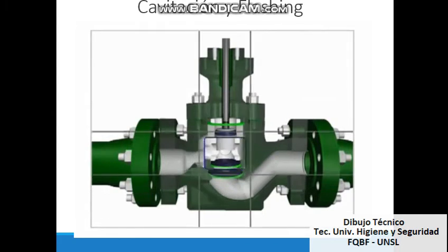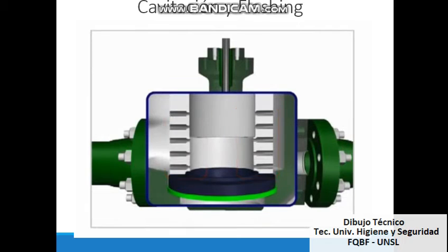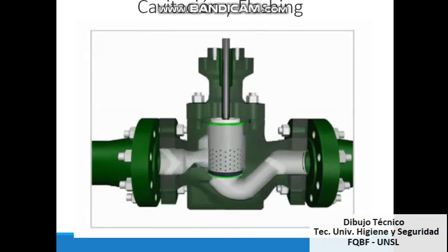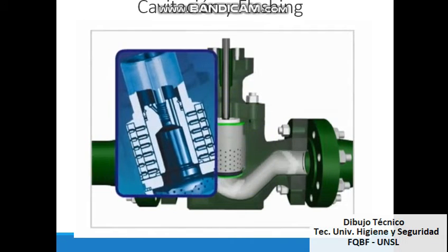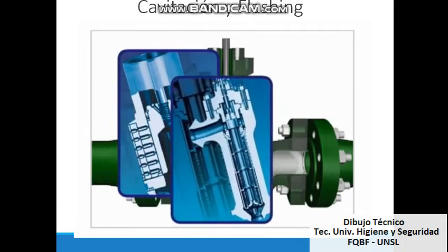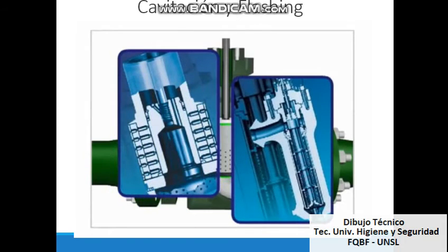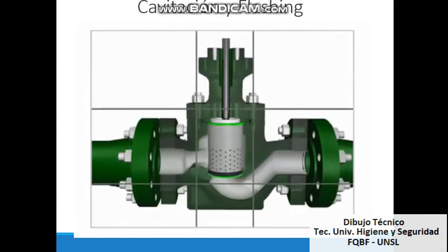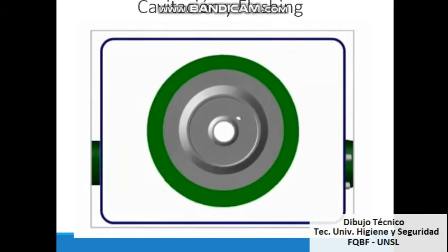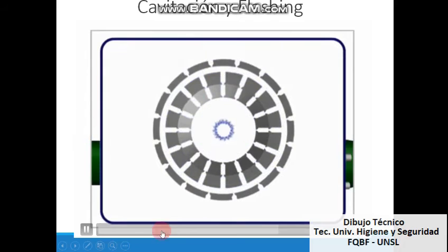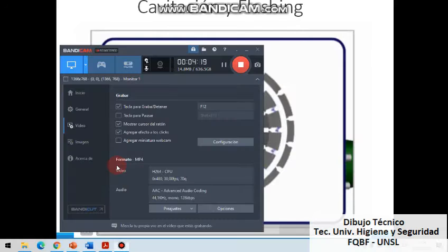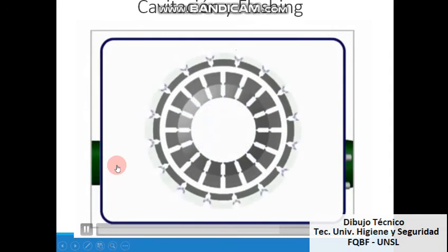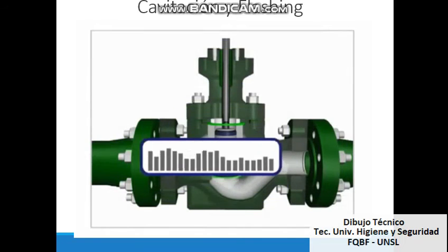Pressure staging keeps the pressure from falling to near a liquid's vapor pressure, which helps prevent vapor bubbles from forming. Pressure drops are staged by the use of expanding nozzles or expanding flow areas. For example, in the Cavitrol 3 valve trim, nozzles have holes shaped to manage flow separation. Multiple small holes shift the noise to higher frequencies.